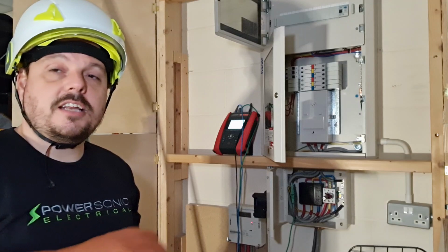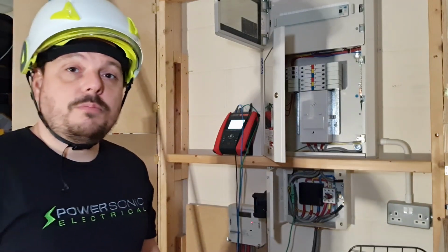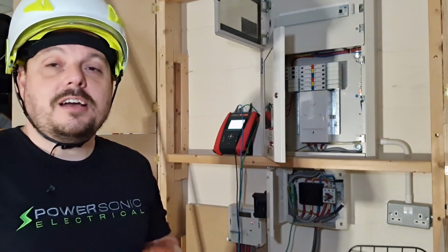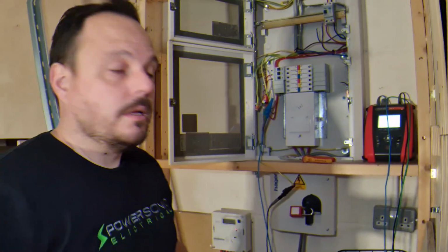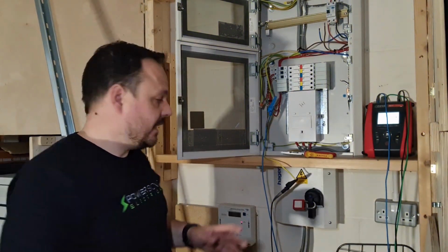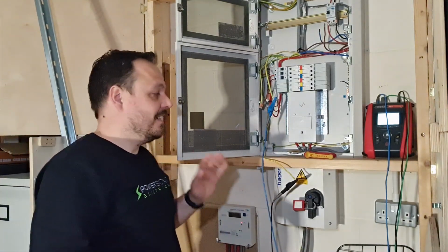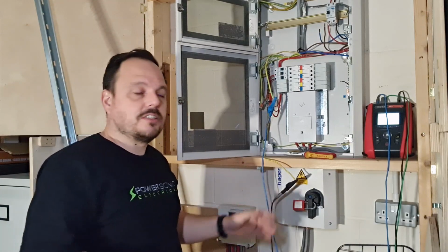I can pop this back together now and cover up those live parts, just shut the enclosure front, and then we'll jump on with doing some dead tests where I can take this PPE off and we'll run through the entire process start to finish and look at the calculations. Okay, so we've got the board safely isolated now. I've put a little lock on, you know, just in case. Obviously there's only me in here, but you never know, you can knock things by accident, so that's not a